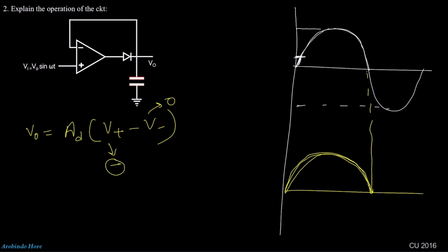So eventually you can see we will get a negative voltage. And we all know if we get a negative voltage here, suppose this is V1, the diode will be off. Why? Suppose this is the diode, here is V1 and here is V2. This is the negative voltage, and at V2 I didn't give any voltage, that means 0.